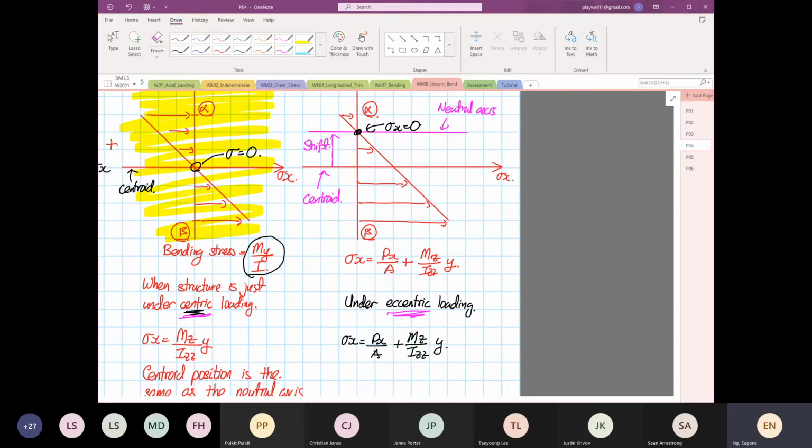That's why when I started teaching bending, or even when I start teaching shearing stress, there's evidence, there's video for it, I never call that point that you identify based on geometry our neutral axis. What do I always call it? I will always address it as what? Centroid. And I want to drill this into you. Don't just follow, okay, we just call it centroid or we just call it neutral axis. No. Neutral axis, if you look at the global topic, neutral axis can be equal to what?